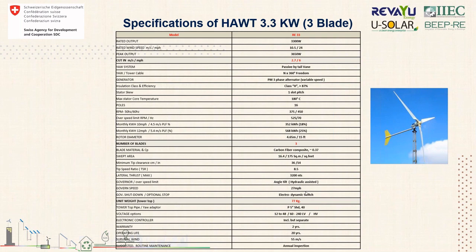Governor speed. Governor is basically a tailwind. Tailwind automatically adjusts and counters the disadvantage of any turbine. As I told earlier, a horizontal axis wind turbine needs to have air striking from the one direction from where the maximum wind is coming. So what the governor does, with the help of this tailwind, is automatically rotate the blades in the direction of maximum wind potential.